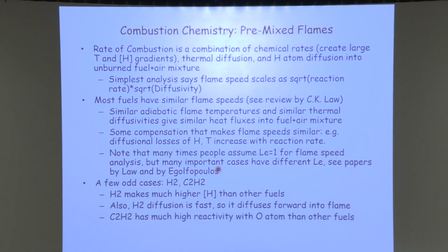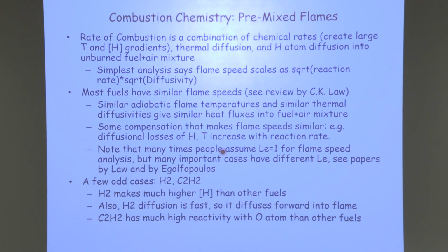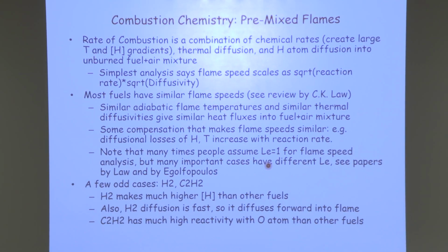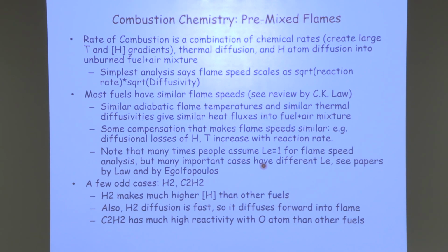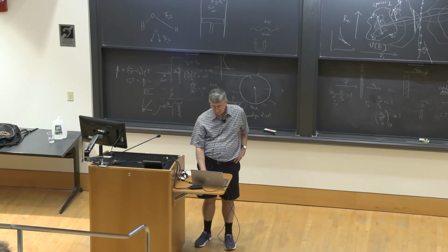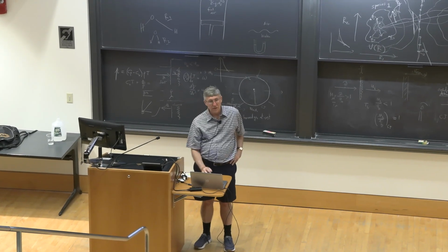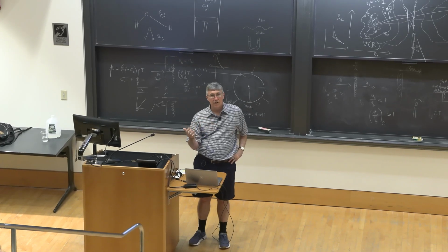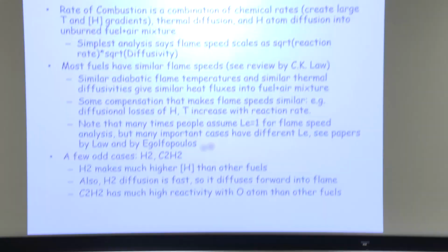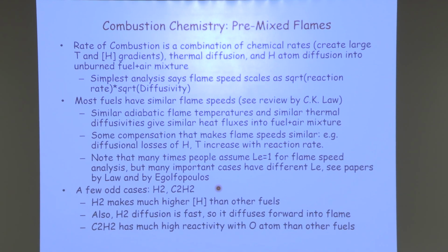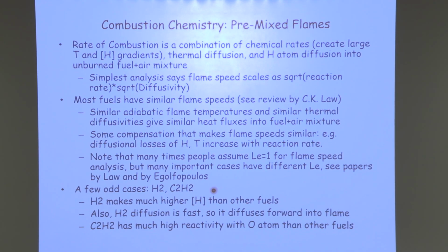And when people do simulations, maybe some of you do this, do you guys know what Lewis number is? How many know what Lewis number is? Yes, okay. So very commonly, people start by assuming Lewis number is equal to 1. But it turns out that in a lot of cases, it's not actually equal to 1, and it's different enough from 1 that it actually matters. And so there's some nice papers by Ed Law and by Egolfopoulos all about the effects and what that actually does to your real combustion.